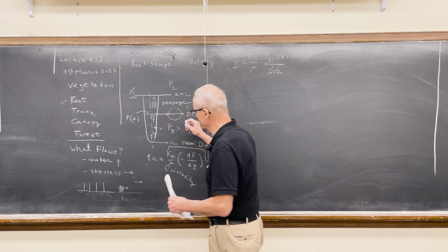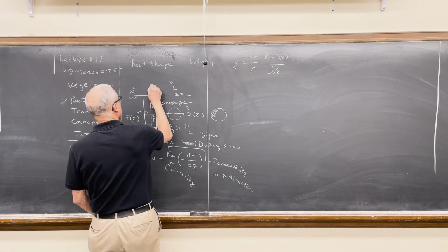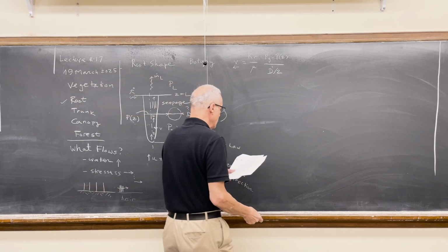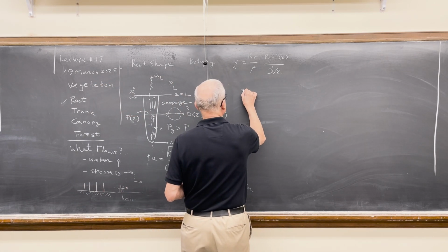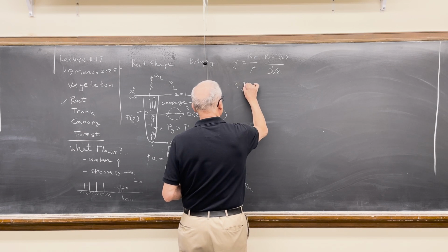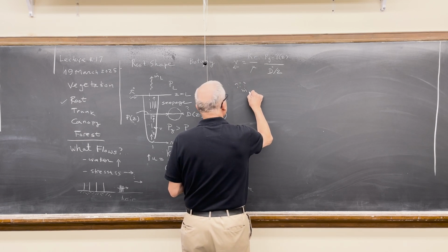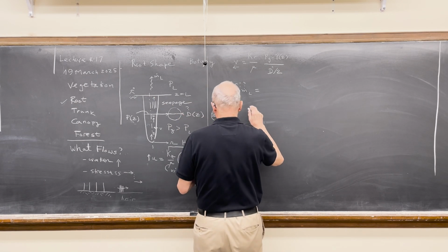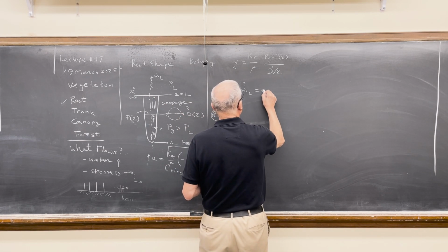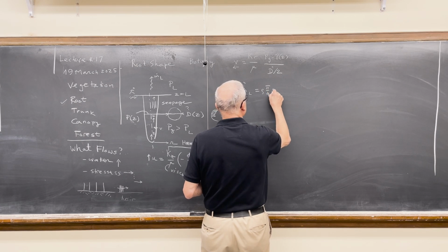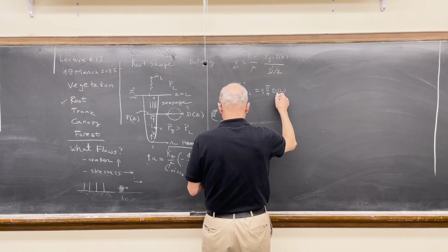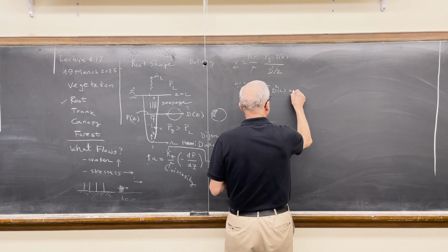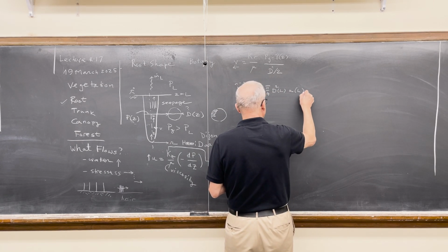Meaning, what is the flow rate upward, m dot at ground level, which equals rho times the cross-sectional area at the top, pi over 4 d at the top to the power 2, times the vertical velocity u at the ground level.